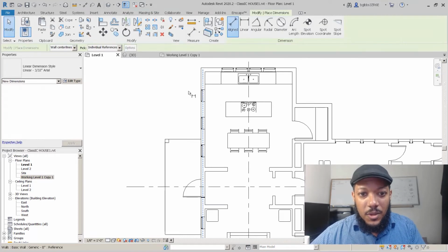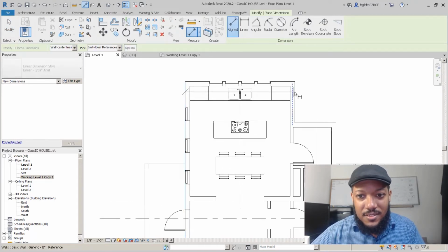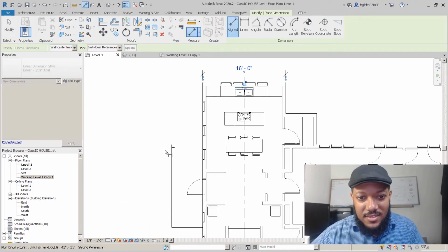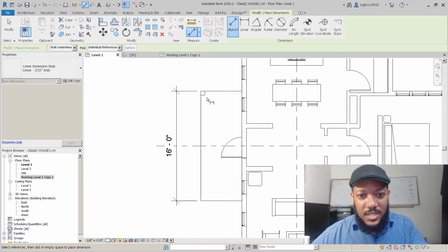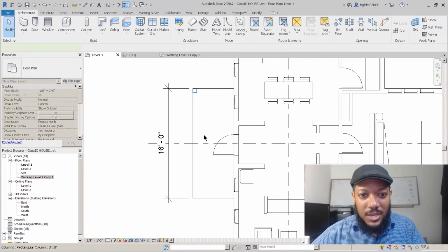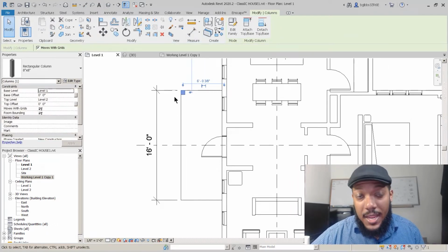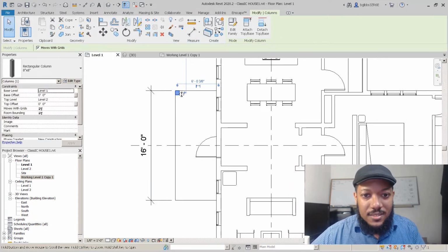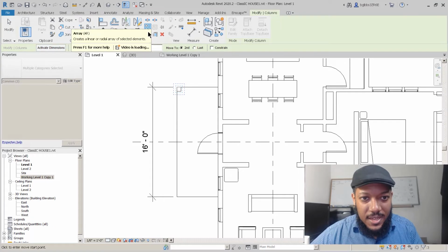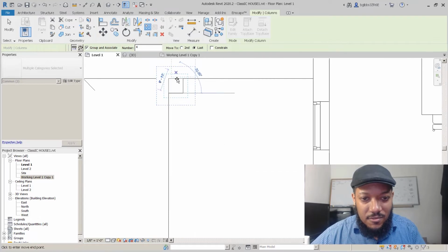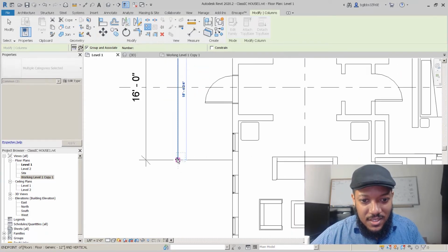So my outside wall dimensions, now we're going to get a little serious, is 16. My porch dimension is 16. You're going to see why that's important when I come up with the model. Now we're going to play with arraying as we're moving this column to copy on our porch. We're going to array here in the modify commands, and we want 4 objects. This is how you array in Revit, a linear array.